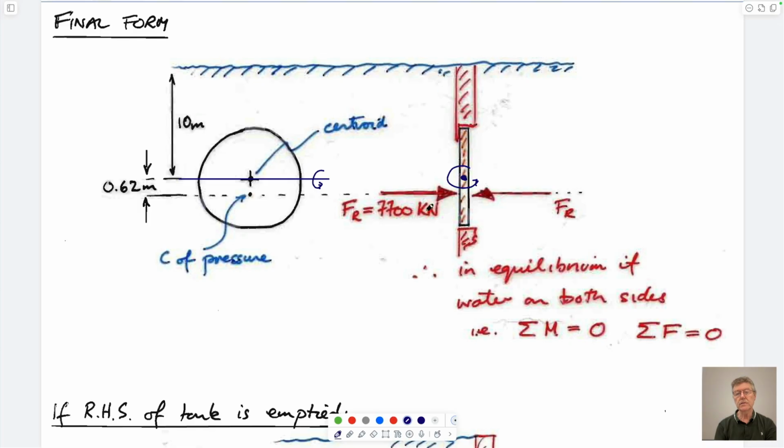And we're going to have water on one side and water on the other side, in which case the force acting on one side is going to be equal to the other side. If you look at the distribution of the pressures, they'll look like this. I'm going to remove that in a second. Highest pressure here, lowest pressure here, highest pressure here, and this amount here is 0.62. This is what we've called delta Y. And so, fine. Has to be acting the same in both sides.